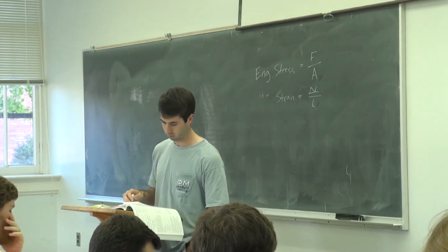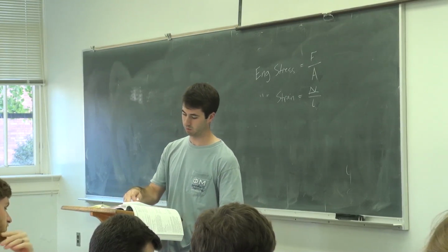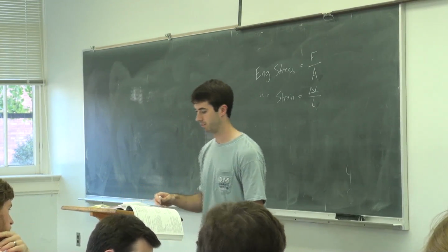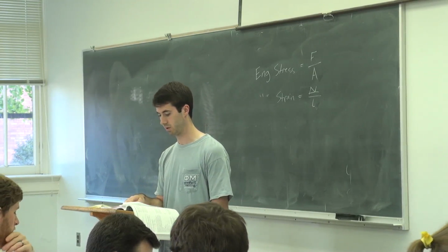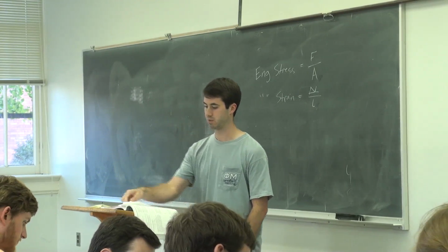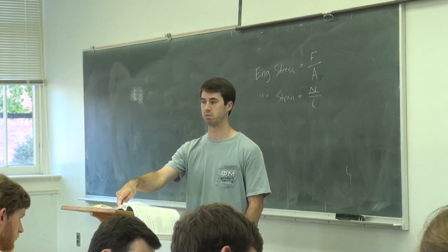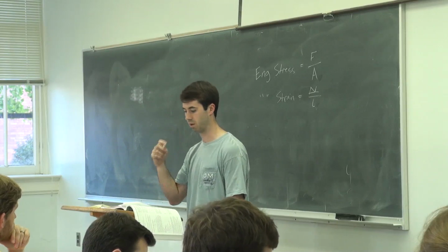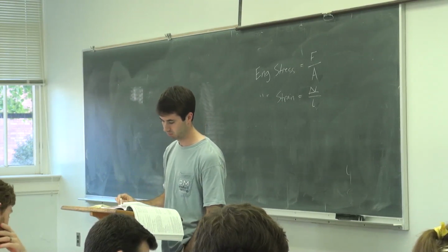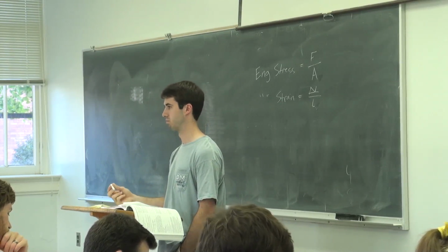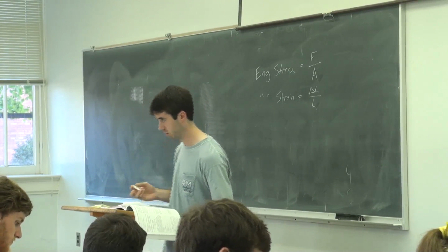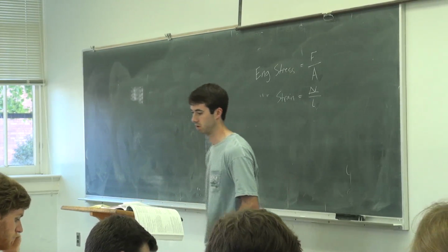So basically, when you see those two lines that take off in different directions, we just say that the engineering stress, the ultimate stress, and fracture stress, that's what we would calculate because we're using the original area and all that. And then eventually the thing breaks. You have seen stuff break in the lab or somewhere before, same as that picture. Any questions about stress strain curves?